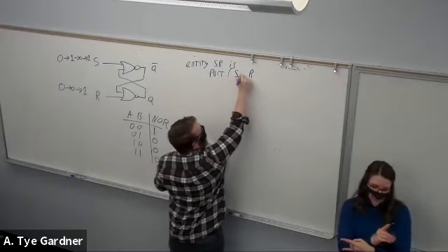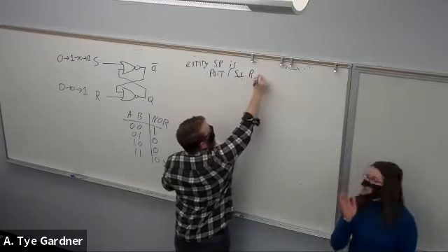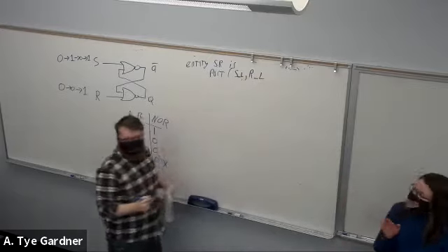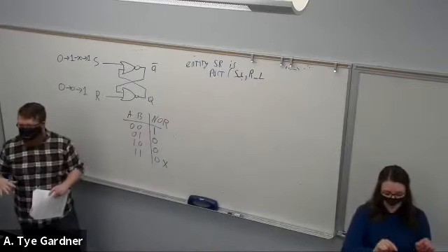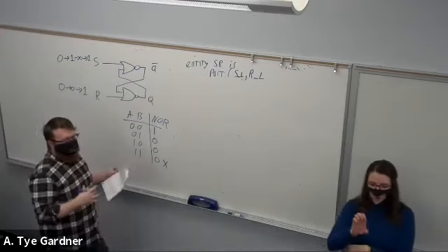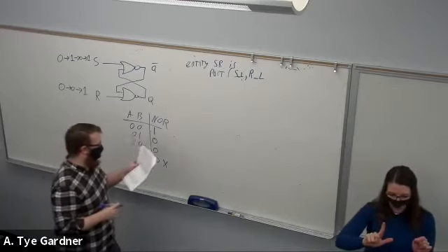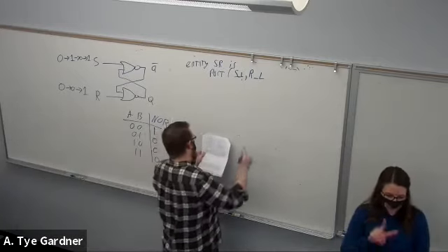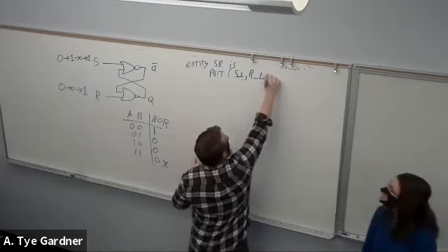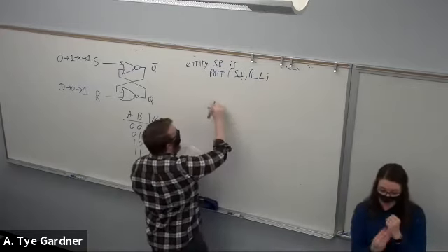So I'm going to do set low and reset low. So that's what I said the difference is between the NAND gate and the NOR gate implementation: the set and reset are active low. So I'm adding an _L to indicate they're active low. And then I need to have the outputs Q and Q bar.